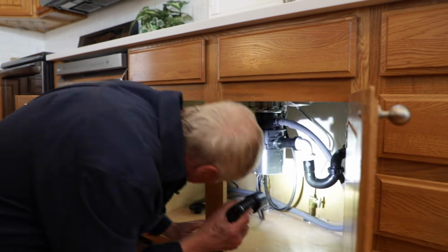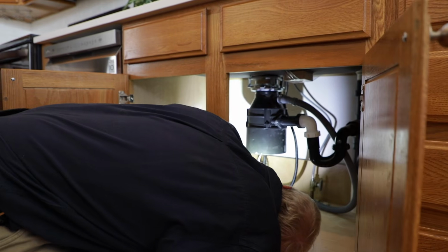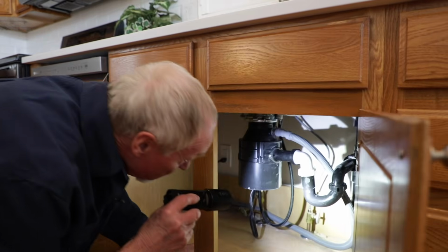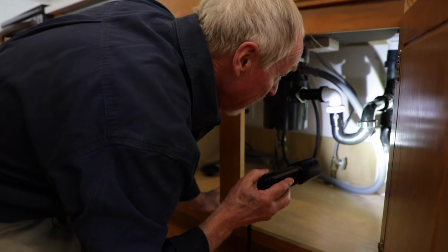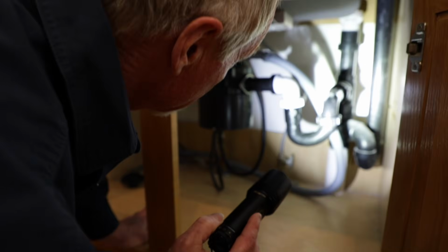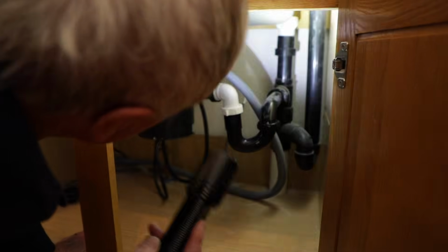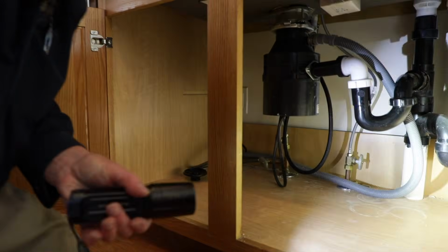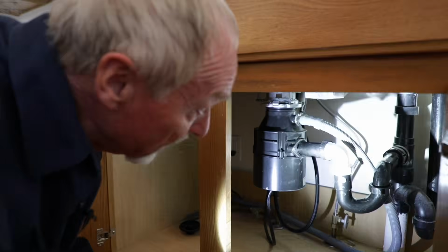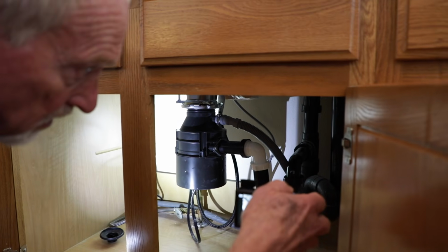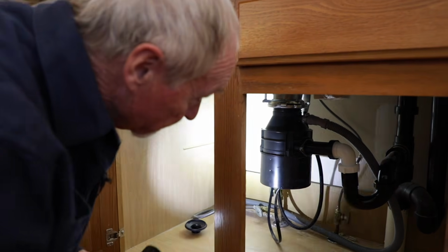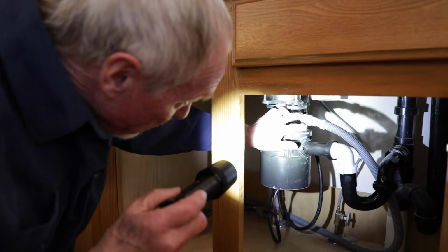Also under here, looking to see our wiring to our disposal looks fine, and our plumbing looks okay. They have a separate drain here for the dishwasher that they didn't use. Shame on them for that. In this case, that would solve our high loop problem if they had, and quite frankly, I'm going to take a photograph of that, and I'm going to have to write a little essay in my report explaining that they did not plumb this correctly, because you should not use the knockout.